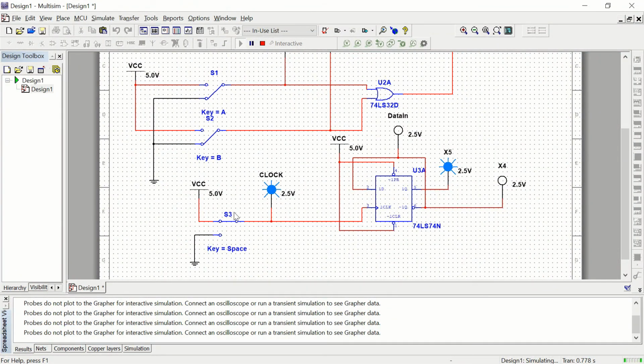And you can see the clock is high, and now we'll make the clock low again. And notice that nothing changed over there. And so you probably thought that every time you do the switch, it's going to flip-flop the outputs, and that's not what happened. And then we'll make it high, and now it flip-flopped. Okay, so clock is high, and now we're 0, 1, and I go down low, and then nothing changed. And then I go high, and they flip-flop. And then it goes low, and nothing changes.